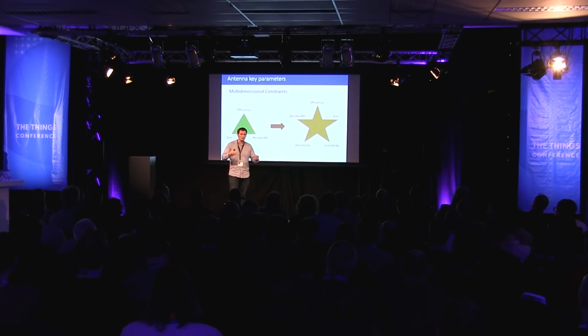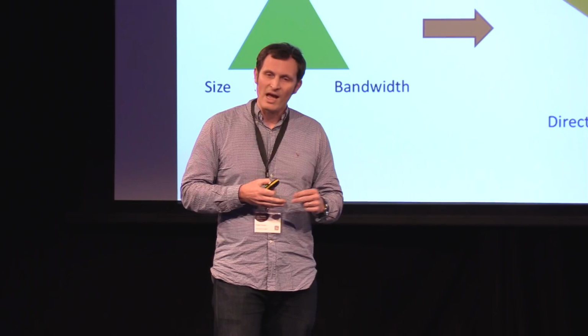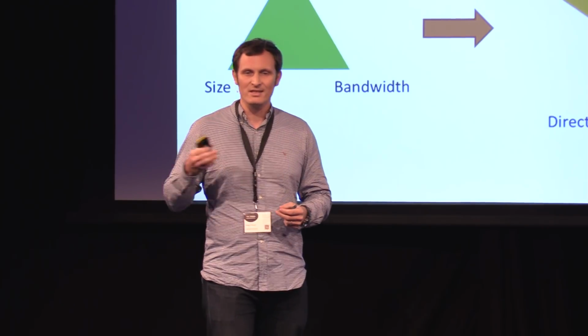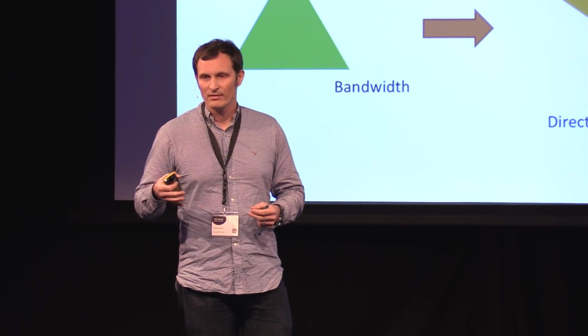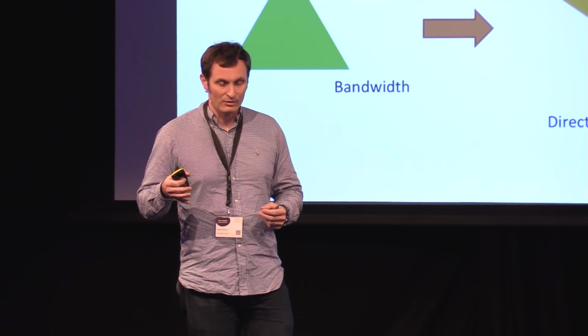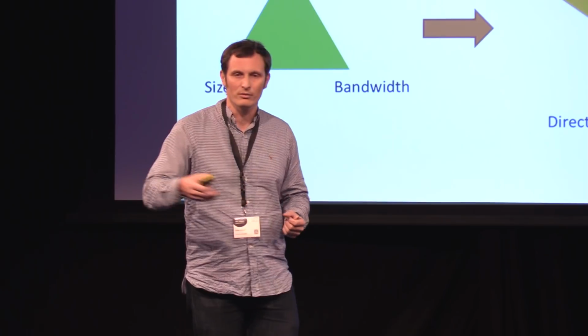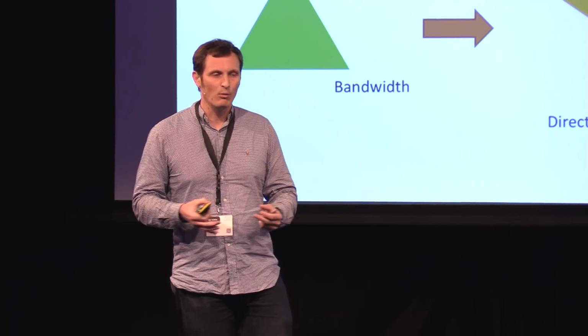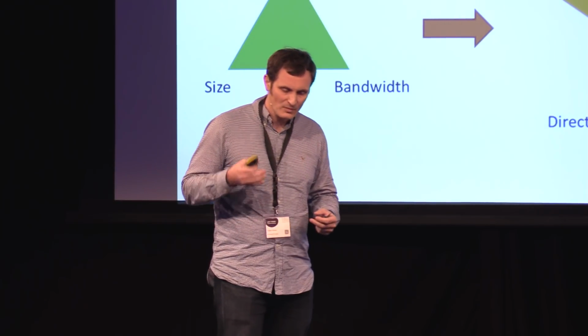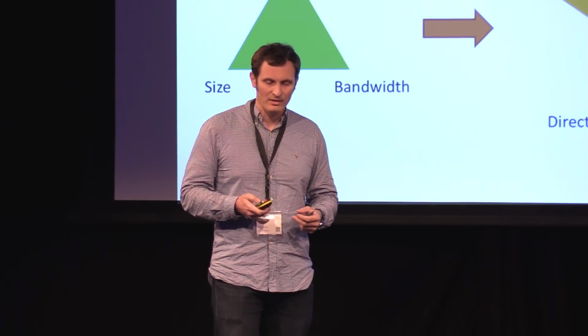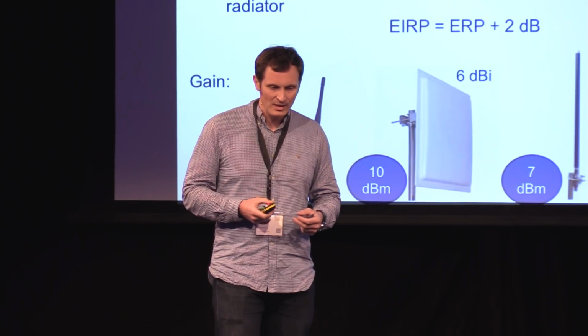So you want to be able to radiate in a specific direction. And also, one important parameter is the sensitivity. You don't want your antenna to be too sensitive to the environment. If you place it on a metallic table or on a wood table, you want to always have the maximum performance. So you are adding a lot of additional constraints.